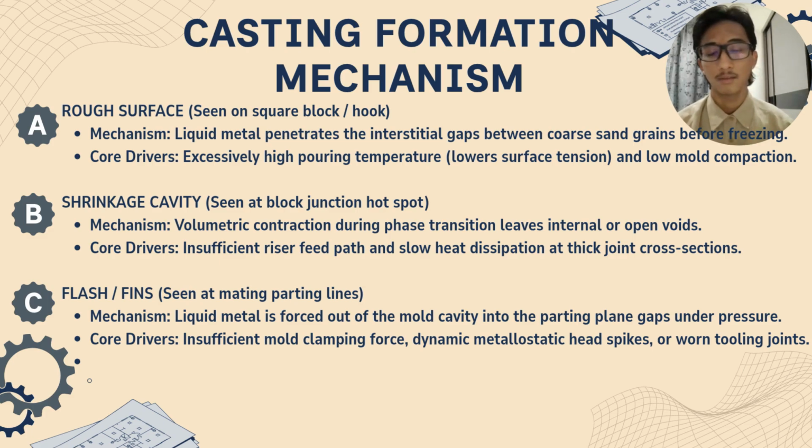It's also caused by insufficient mold clamping force, dynamic metallostatic head spikes, or worn tooling joints. If you use a poor quality joint, or don't clamp the mold cavities properly, or the tool doesn't work very well, flash will happen and it will ruin the product.